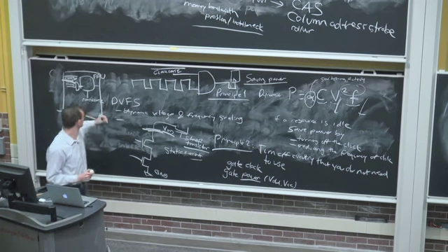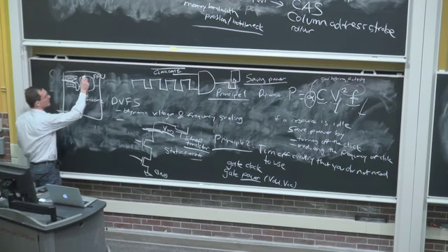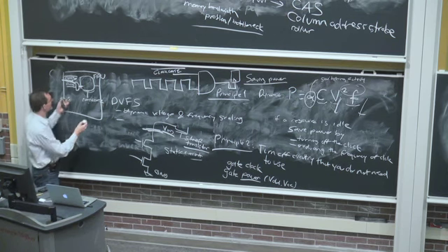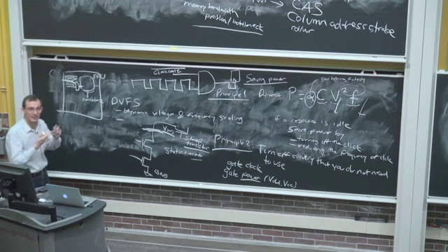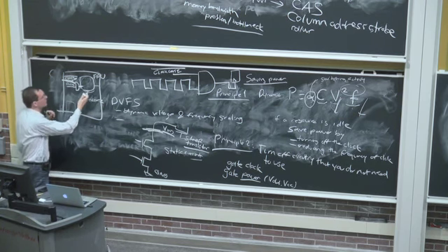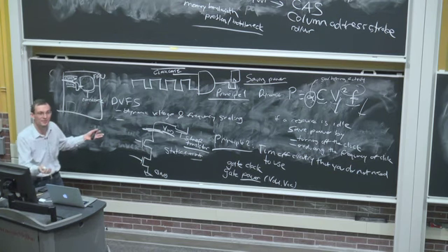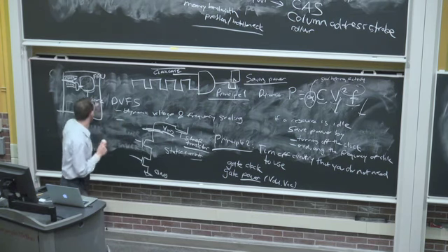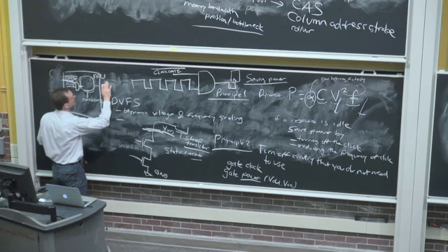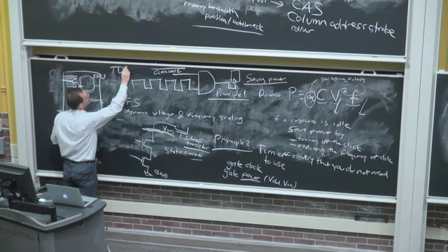Why? Because now you're consuming power unnecessarily, which means that you cannot put another core on the chip, perhaps. Right? You cannot put more cache on your chip because you're not managing your power intelligently. And remember, there's limited power. There's a total design power, or thermal design point also.